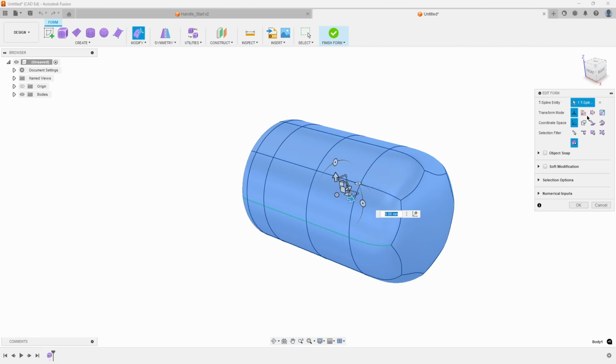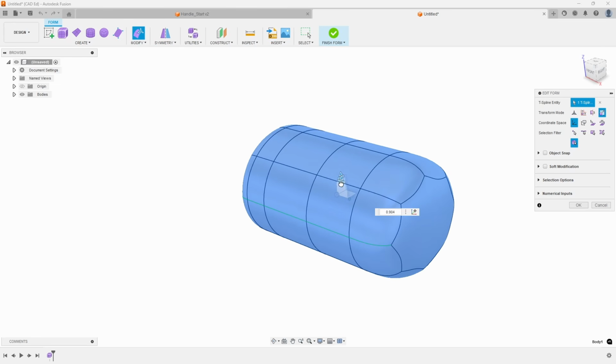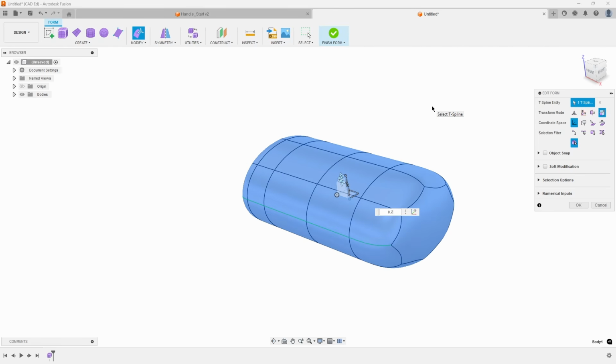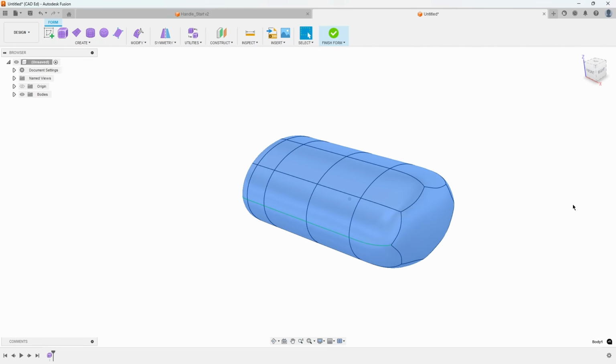In this case, let's select the Scale transform, and you will notice many of the icons disappear. Select the horizontal scale bar in the XZ plane and drag it down to scale the whole model down in that direction. Type in 0.7 for the scale factor and press OK.